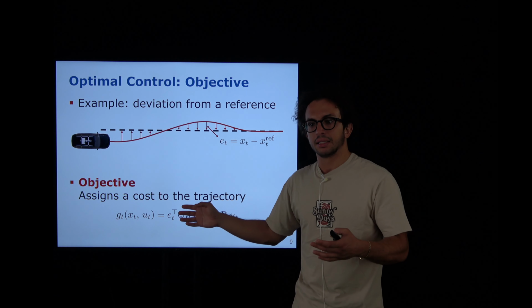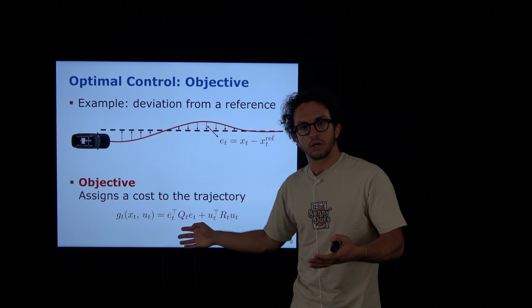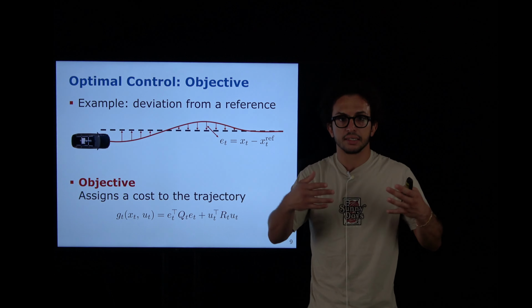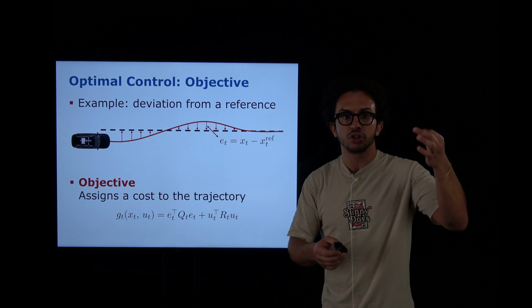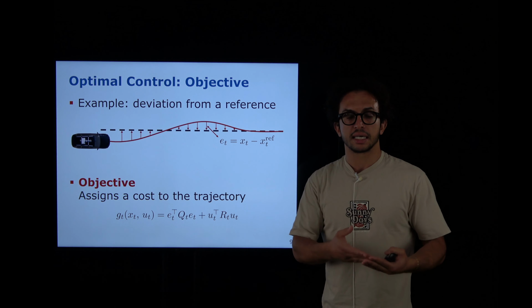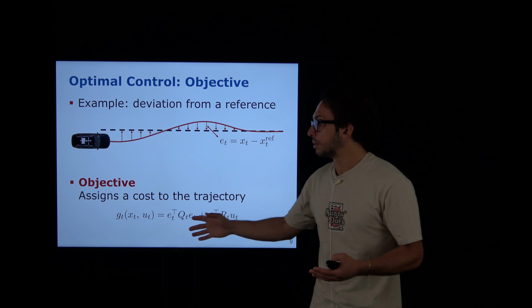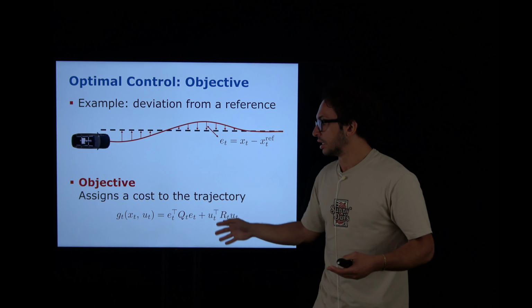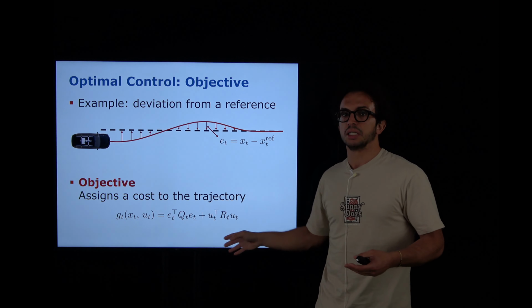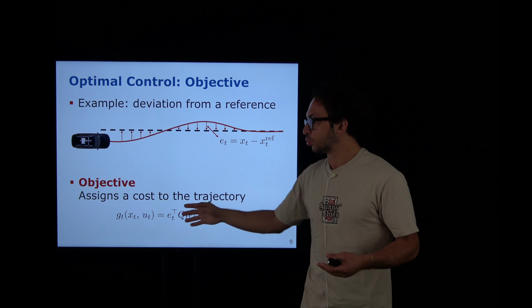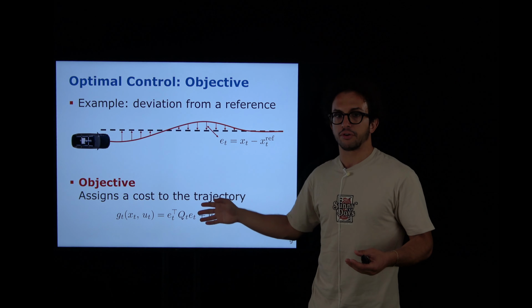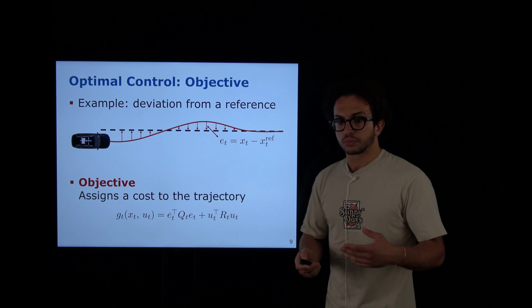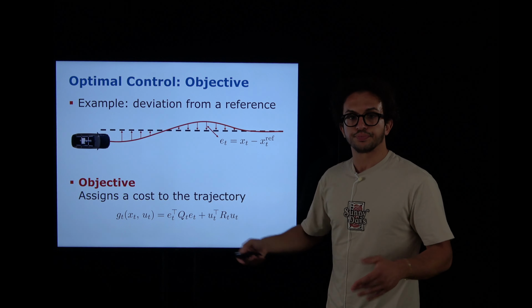So the result of the control problem will not be maybe as perfect as in the PID case, where we know that the integral action brings the steady state error to zero, but it will be a minimization. So there might be some residual error. So this is the concept of the minimization of something. So we will not have for sure error going to zero in theory. So this is the cost function.